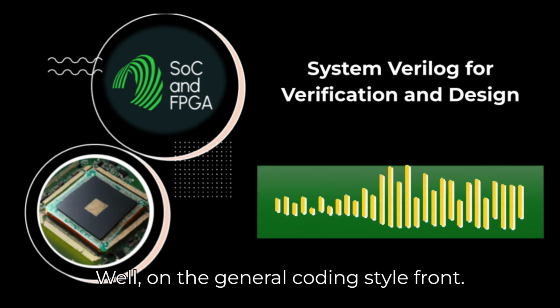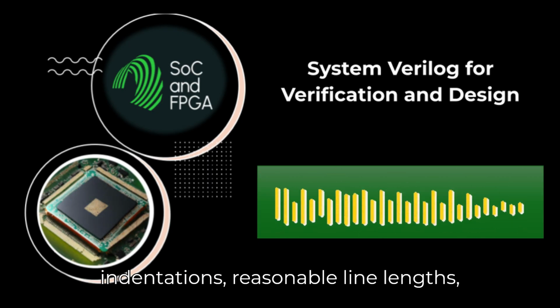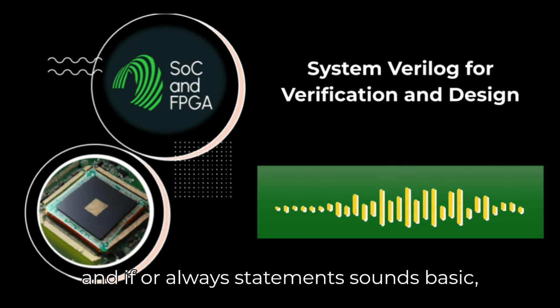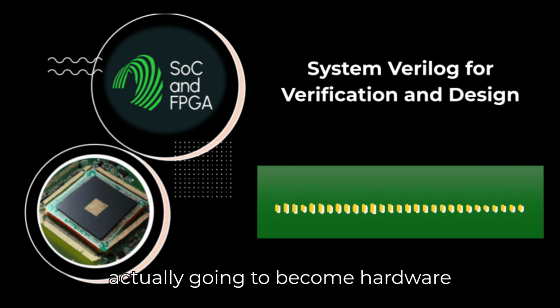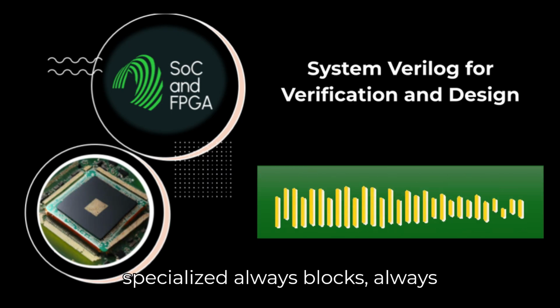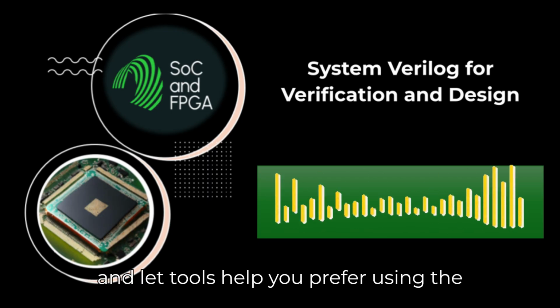Well, on the general coding style front, consistency is king. Consistent indentation, reasonable line lengths, always using begin and end for blocks and if or always statements. It sounds basic, but it prevents subtle bugs and makes code readable. And for code that's actually going to become hardware, synthesizable design, definitely use the specialized always blocks, always_comb, always_ff. They document intent and let tools help you.